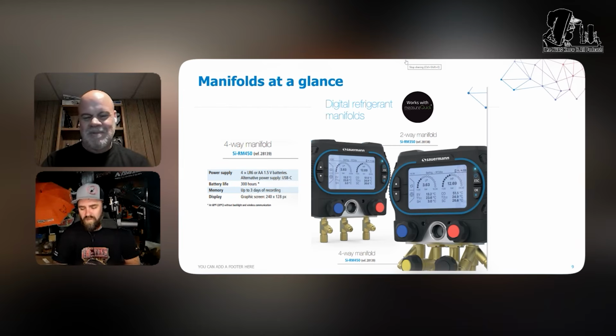Awesome. The other thing that I want to bring up too, along the same lines of what I said, is there's still a market for it. Now, a lot of techs are moving to the practice of going from the equipment straight to the vacuum pump with a single hose. But you have a 4-port manifold on there, and pretty much every manufacturer still has a 4-port manifold. And anytime you talk about the single hose or 2-hose setup coming straight from the equipment to the vacuum pump, you always get half or more of the techs saying they still pull with a manifold. So again, there's a market for it because they're still comfortable doing it that way.